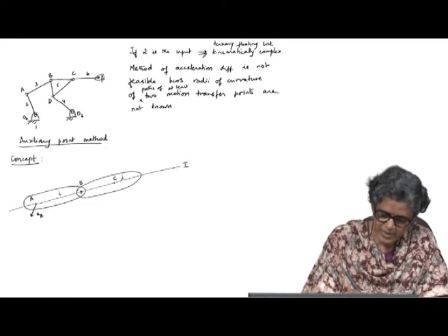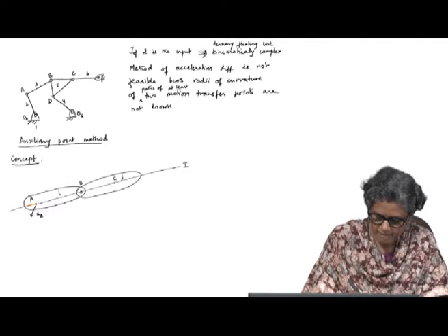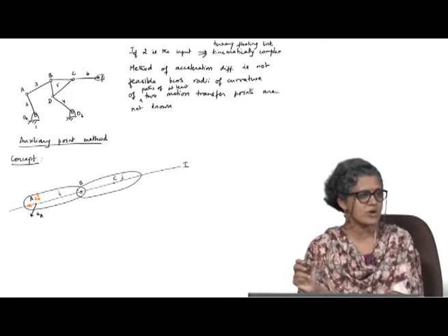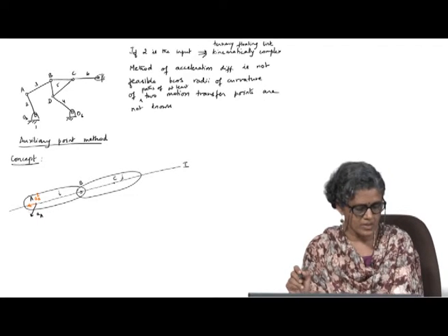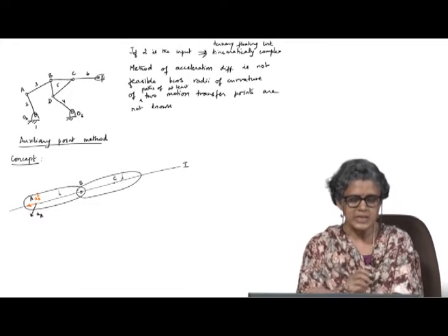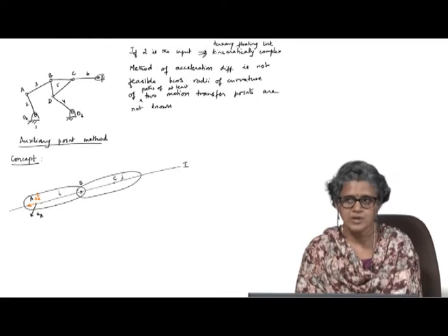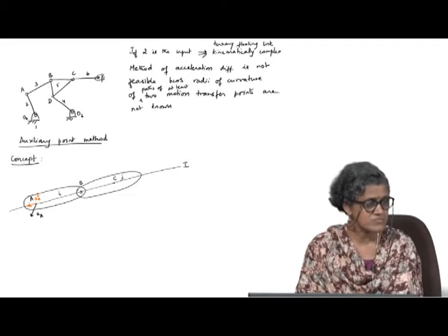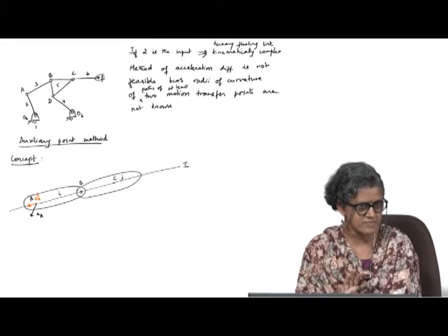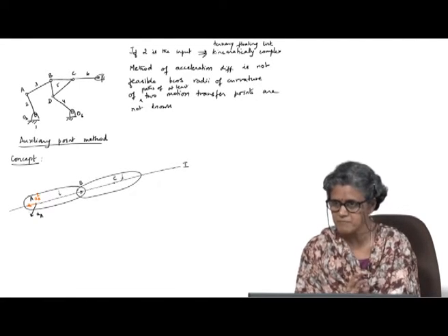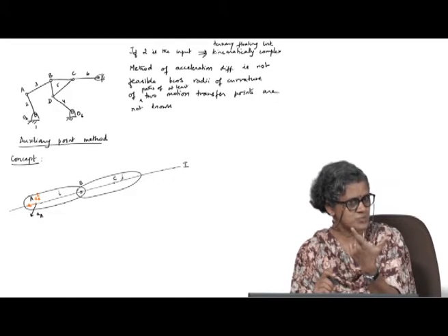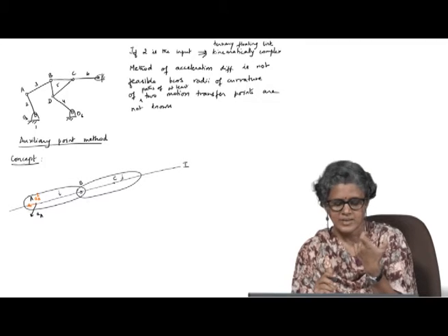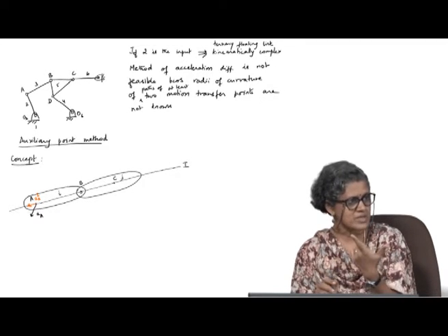Okay. So, now if you look at this, this is the acceleration of A along this line 1, auxiliary line 1. What will be the acceleration of point B along this line? Will it be the same as this? Velocity was easy to visualize. Velocity is going to be the same because the two points are on a rigid body and they can't move towards one another. In the case of acceleration, how is B moving with respect to A?